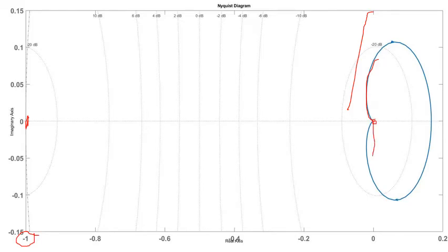Look here, this goes with this 0, and there is no encirclement of -1. It starts with a magnitude for omega equal to 0, encircles in this way, and goes back to that value. So omega equals 0 plus is here, omega 0 minus is here, omega infinity plus is here, and omega infinity minus is here. This is the curve we got in our normal method also, and that can be verified using Matlab also. So the system is stable.